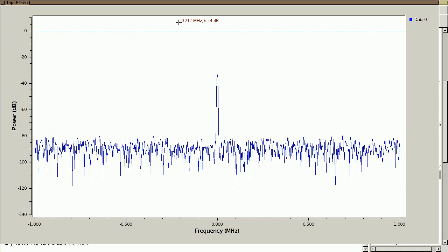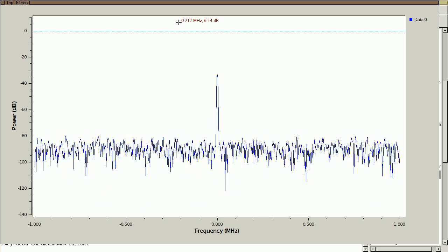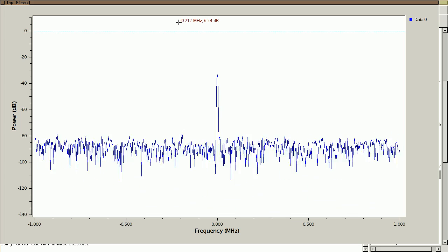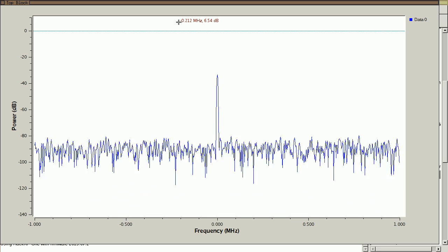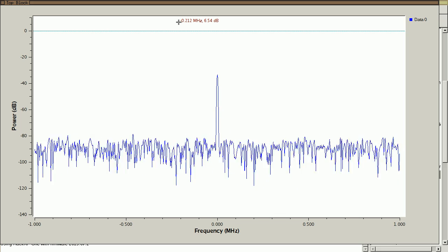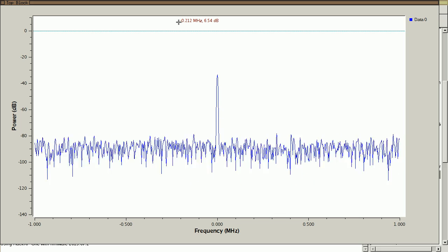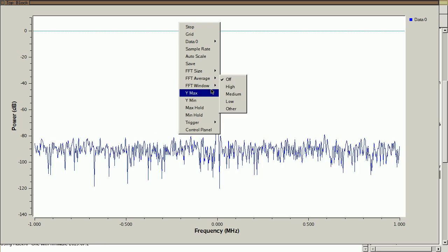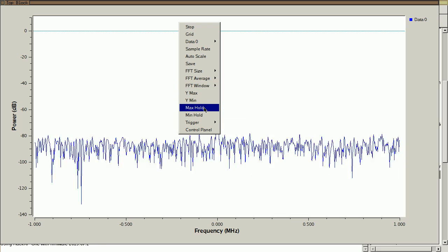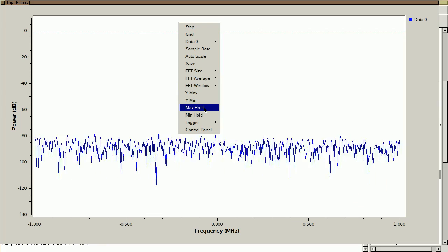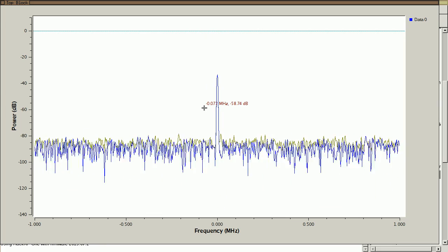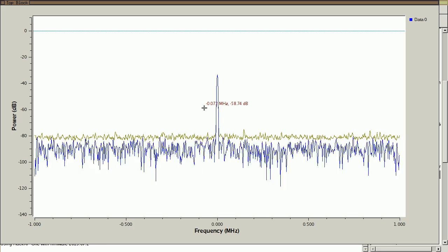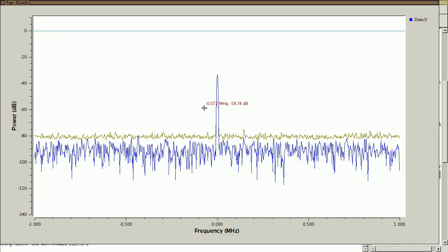One thing you'll notice that's different between the WX GUI FFT sink and the QT GUI frequency sink is that the QT GUI does not have some of the controls that you're used to on the right-hand side. But if you use your third mouse button or your middle mouse button, you can bring up a menu that has a whole bunch of different options, including things like max hold that we've used with the WX GUI FFT sink. So let me try max hold, and I'll pick up my remote control for the toy and try to move the car a little bit and see what happens.